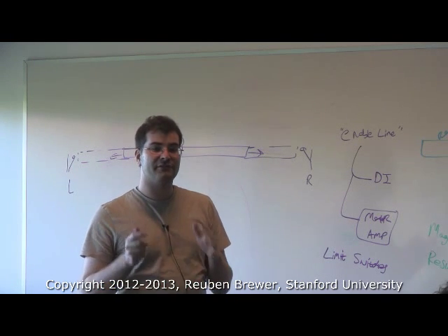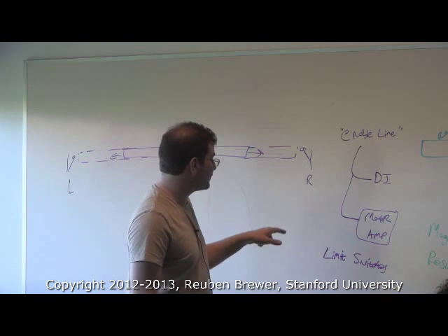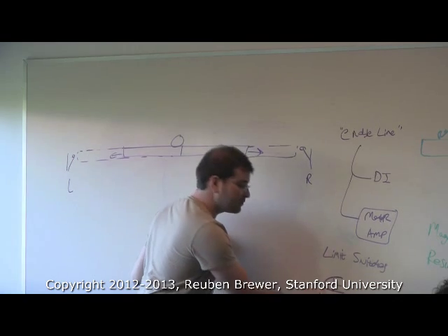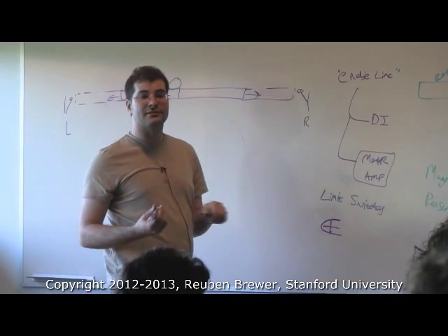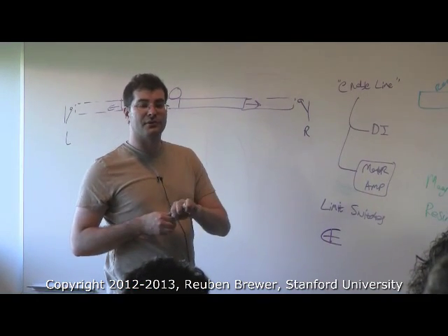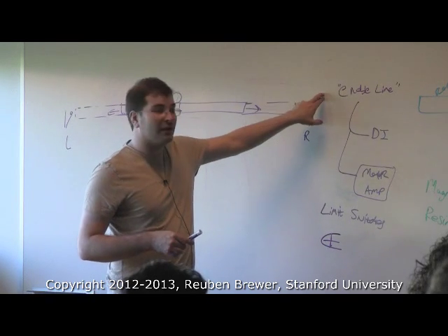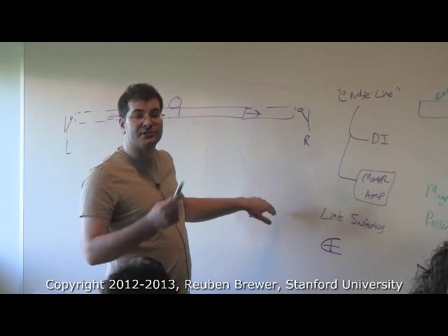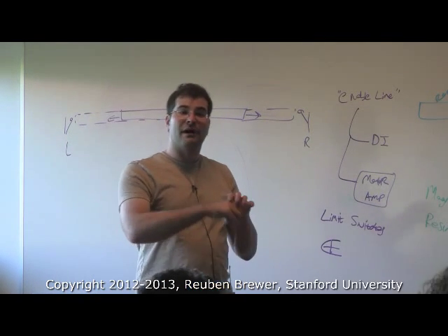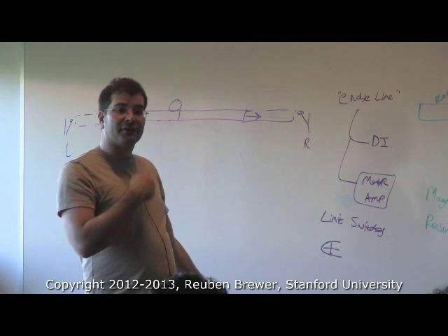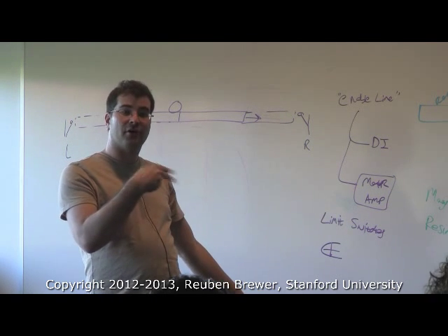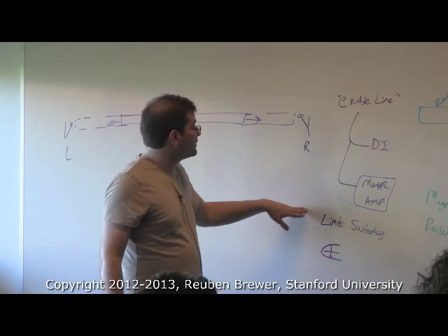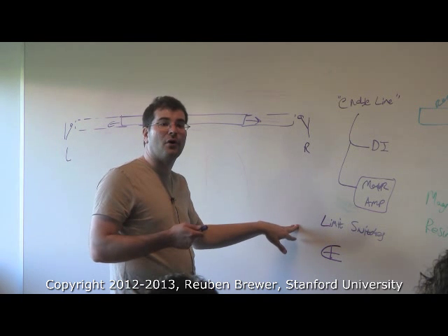And so for safety, you always want multiple tiers. I literally have one that is essentially a relay, and it just takes the plug from the wall and yanks it. It's just a solid state relay, or you could even do an electromagnetic one. Then you have an enable line going to your motor amp. That same enable line also goes to a digital in. So if your robot hasn't frozen on the computer, it's a soft stop. It doesn't have to hard reboot the computer. So basically every signal goes everywhere except for the death switch, which is me yanking from the wall.